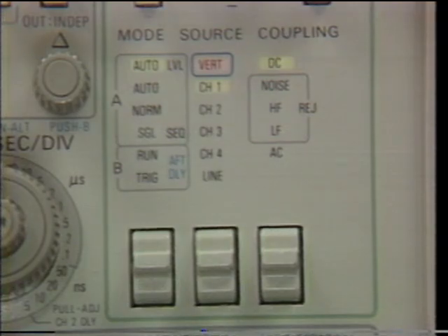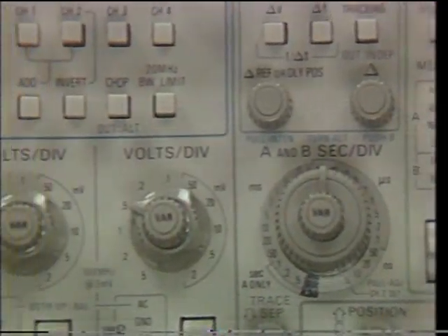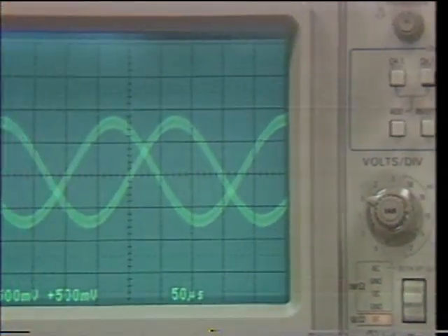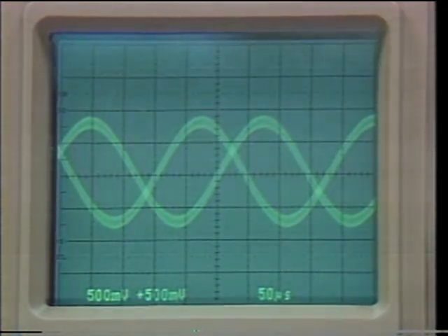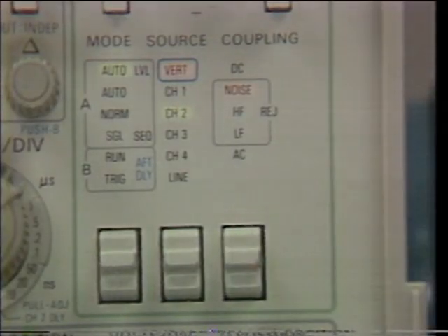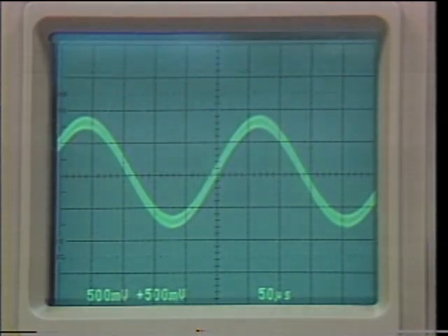Now we have displayed on screen here a signal with superimposed noise. Now the noise has sufficient amplitude to trigger the sweep, and so we are seeing a trigger on each slope of the lower frequency signal. To eliminate that, we simply switch to noise reject triggering, and that low amplitude noise is rejected. Noise reject is an amplitude discriminating mode, which also preserves the trigger level readout, except in this display we are generating this mixed signal by using the add vertical mode.